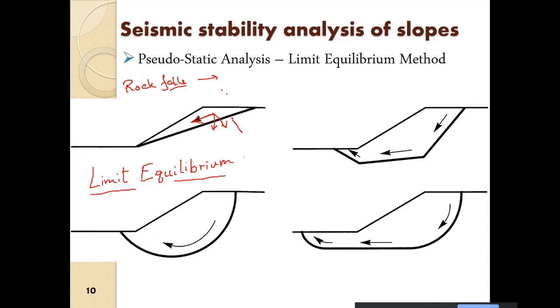The normal component gives rise to friction, and the friction is basically the stabilizing force. There is none other than that. And then there is the tangential component of the weight itself, due to gravitational or inertial forces, so this mass tends to slide out.